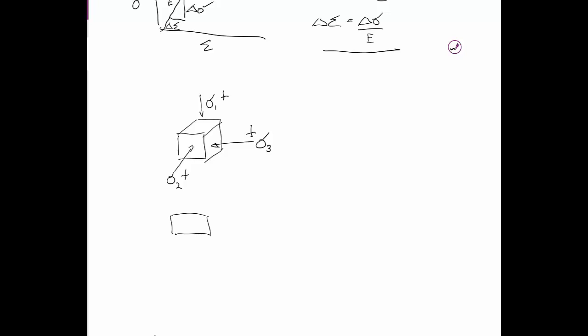But a sponge sitting on your bench, and there's a vertical stress, sigma 1, and a horizontal stress. I'll call it sigma 3 just because that's a convention we're going to use later. And you know that's just air pressure acting on your sponge. But it's really just sitting there quite happily, like that soil element above it is. It's been there for a long time. And it's a good model. That's positive, and that's positive.